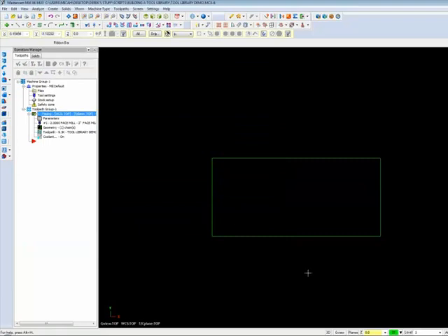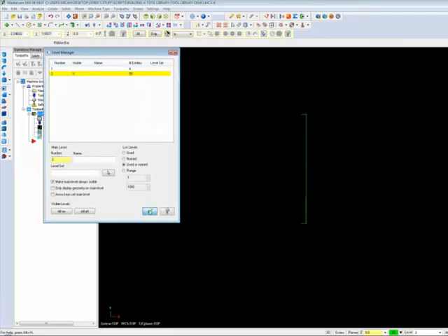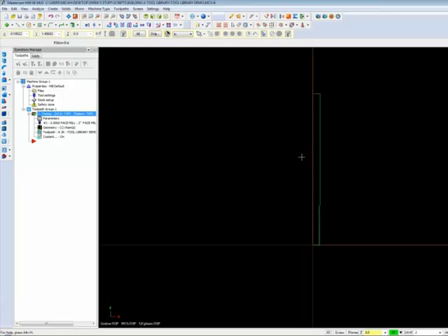To save you the tedium of watching me draw individual threads, I've created the thread mill geometry on a different level. There are a few rules to follow when creating tool profile geometry. The center of the tool tip should sit at the Mastercam world origin. Only half the tool needs to be drawn, and the two endpoints along the y-axis can't be connected to complete the shape.